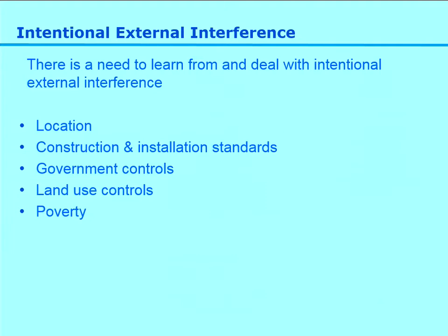Right, now, one thing I do want to draw your attention to: we've talked about a lot of incidents, but in reality, there are only 2 failure modes of pipelines. Pipelines are very simple structures. The first is a leak, and the key thing about a leak is it's small and it's stable. In other words, once you've got a through wall damage site, that damage site is not going to change or extend as a result of the release.